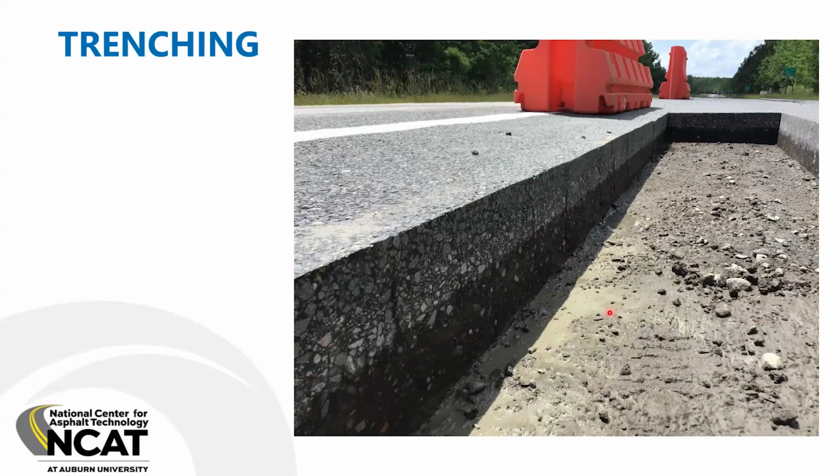Just a personal tip that I'll mention is when you pull these slabs out, I'd push them off to the side of the road and just put them on the shoulder, because obviously this pavement is coming out. You're going to have to mill it. So the milling machine will need something to ride over. So it's just real easy just to push those slabs back in where they came from. And sometimes they'll completely disintegrate on you, but it's much better than having to go and get a load of crushed rock or RAP to fill that hole so you can mill it out.